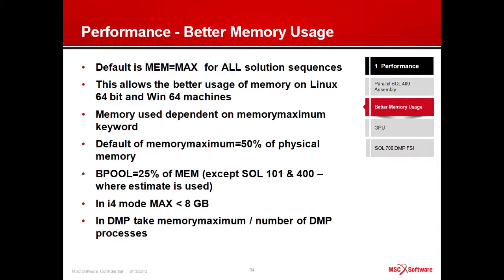Another improvement has to do with memory utilization. We started this in 2012.2, and it was for SOL 101 and SOL 400. Now it's available on all the solution sequences. It's known as memory equals max. It is now the default in MSC Nastran 2013.